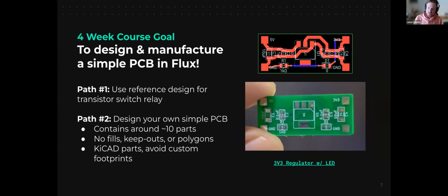This last one, with the part number XY301V, has a footprint indicated by this icon, and it also has a 3D model. And it has a usage count of 7. You need to pay attention every time you add a part from here to your canvas that it has a footprint and 3D model. Later on, I'm going to tackle how to add the footprint and 3D model. But for now, let's just drag this one to the canvas.